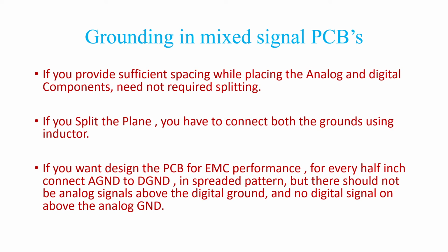If you want to design the PCB for EMC performance, one more method can be followed. For every half inch, connect the analog ground to the digital ground in a spread pattern, but there should not be analog signals above the digital ground and no digital signals above the analog ground.